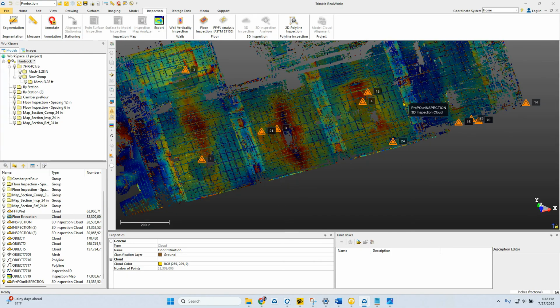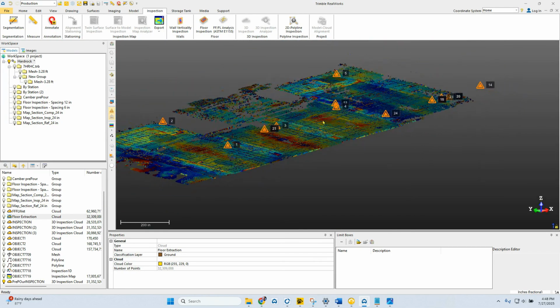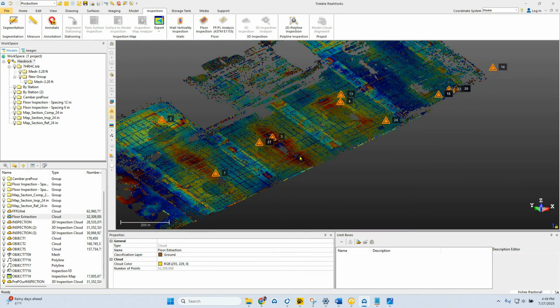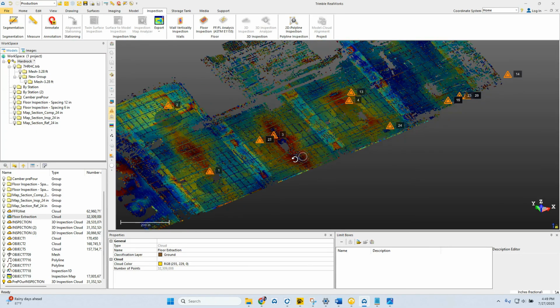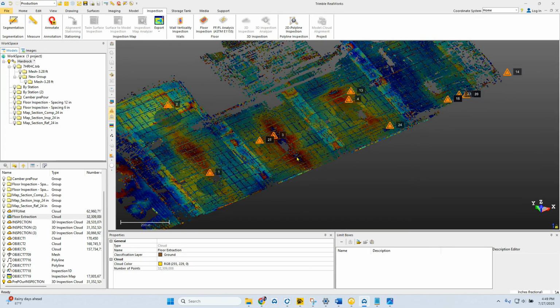A lot of times FL isn't even included on an elevated deck because it's hard to make the concrete contractor responsible for that, as the floor below may shift. But with this information, I can at least tell them if the camber or the plywood or the formwork is good before we get there, because it's hard to pour a flat floor when you have to hit 8 inches if the deck below it isn't flat.